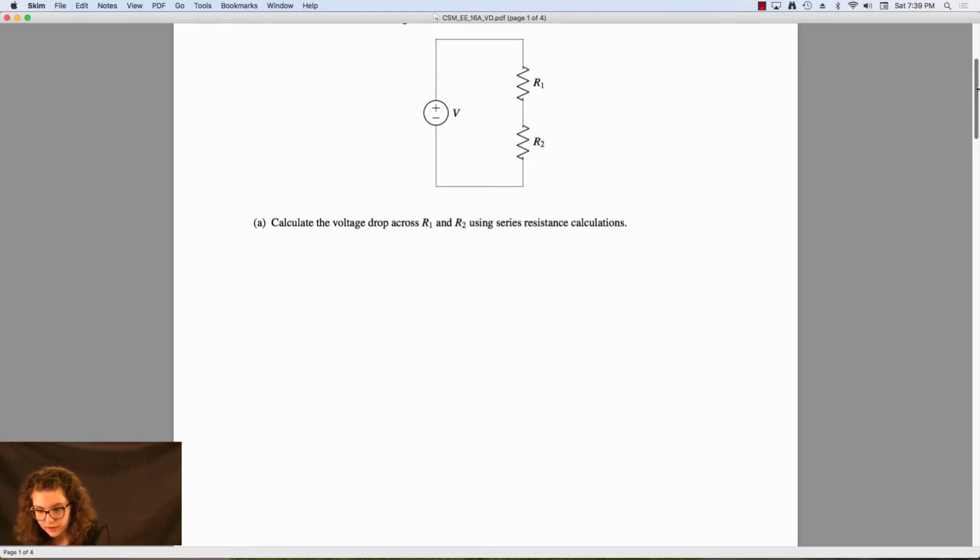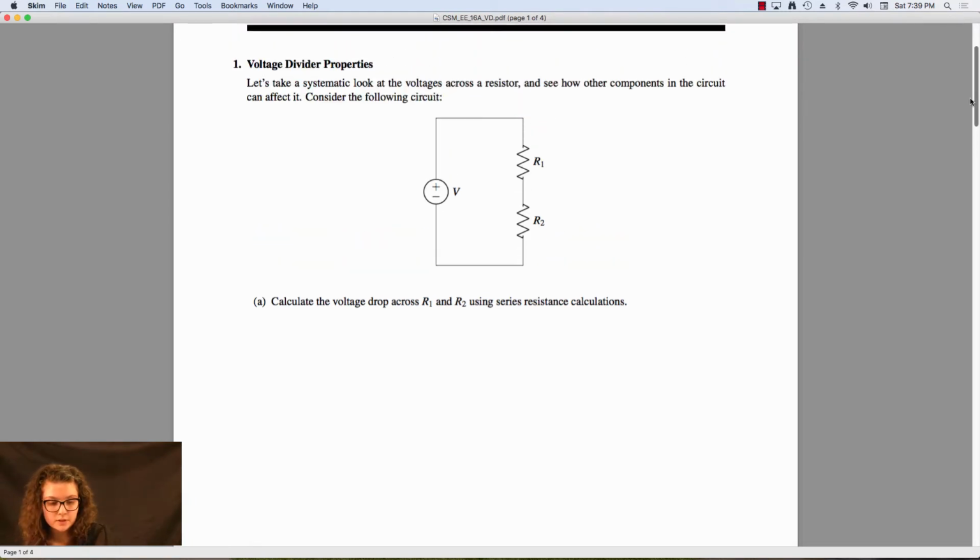So first thing we do for this is we're going to label our nodes, our currents, and passive sign convention. So in here I see three nodes we can create. One node right here, U1, U2, and U3. So how I identified these nodes is I said these are all the nodes that are in between two non-wire circuit elements. So another thing we can see is we need to ground the circuit. So I choose right here.